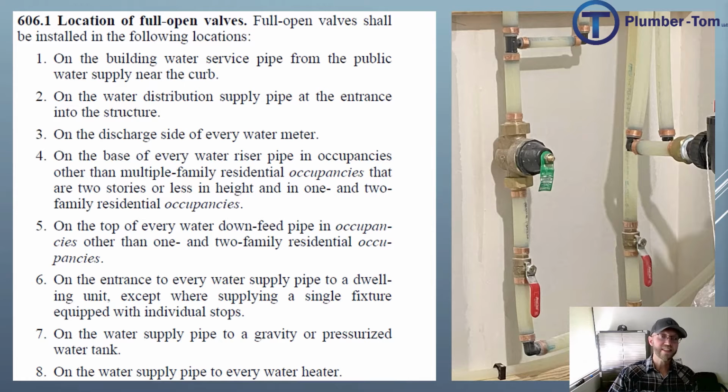At the top of every down feed, I've seen that too. Water goes up to the top of the building and feeds down, or maybe it comes from a tower on the roof. That's where you would want a shutoff valve as well.